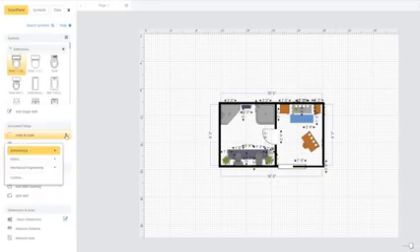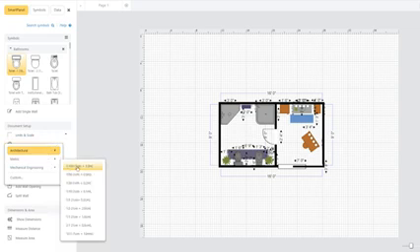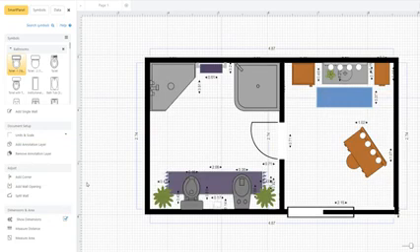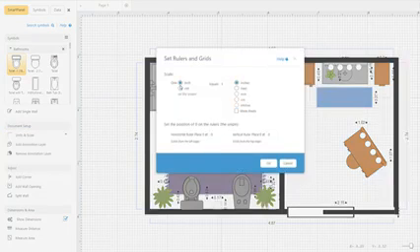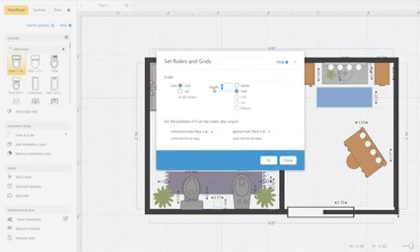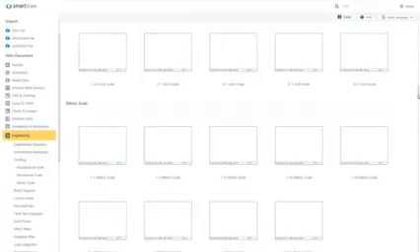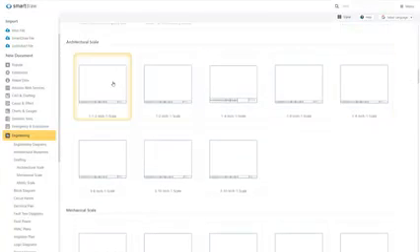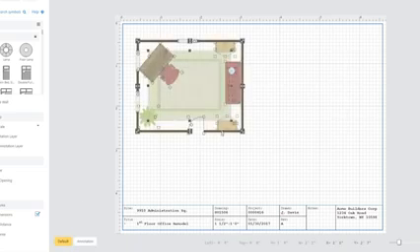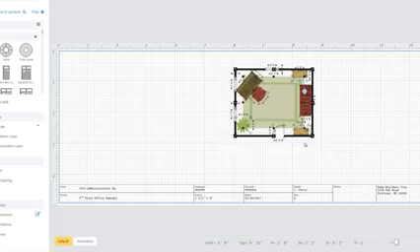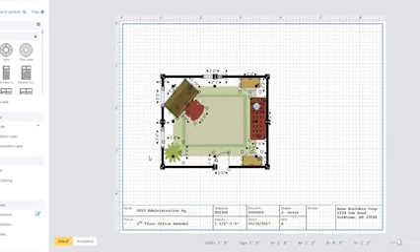You can draw using any scale selected from the standard architectural, civil engineering, mechanical engineering, and metric scales. You can also define your own scale if it is not among the standard scales offered. You can change the scale of any drawing at any time. You don't have to choose this before you start drawing. You can also add a scale-independent annotation layer. Add the scale, author, and other information about the diagram just like you would in the page view in a traditional CAD program. This annotation layer automatically adjusts its size and position as the drawing area or paper size changes.